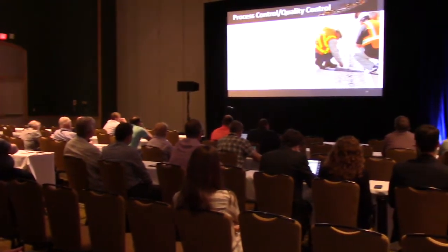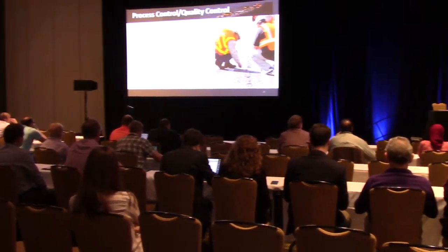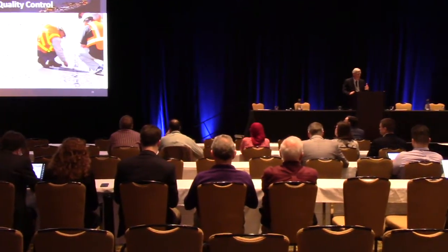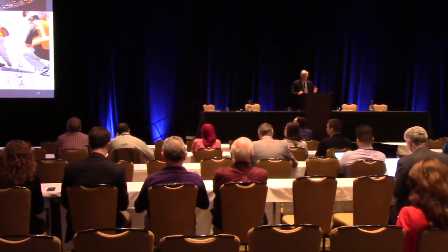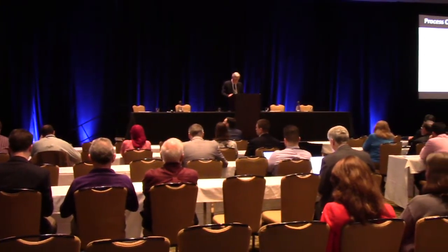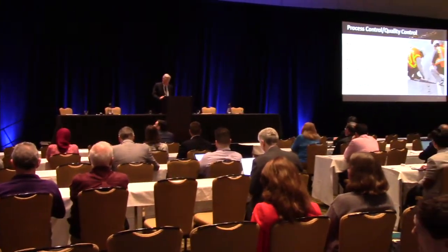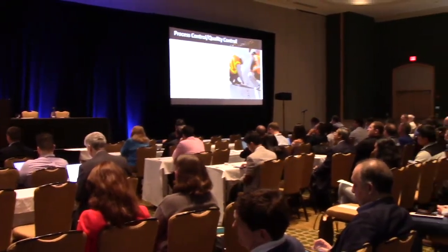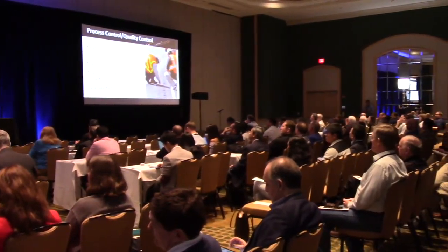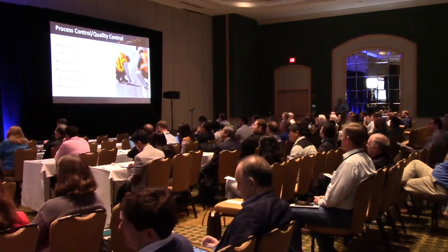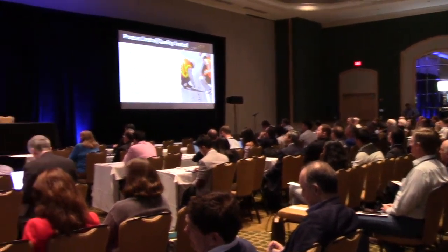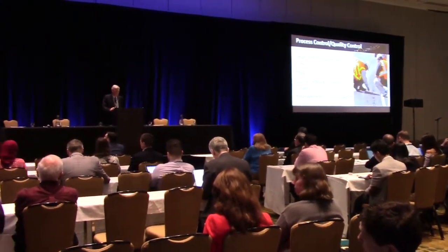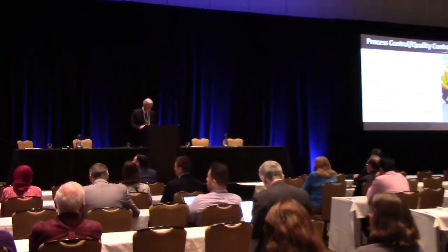I think this is a huge area. I know we've had at least 2 national initiatives that I'm familiar with trying to develop more rapid tests for quality control, process control, or quality assurance for that matter. And we haven't done a good job at it. I don't think we've seen any major breakthroughs. We've got a little bit quicker, cleaner way of determining asphalt binder content as an example of a successful project, but we still do a lot of sieve analysis the old-fashioned way, and we do a lot of other things the old-fashioned way. We need some major breakthroughs here.